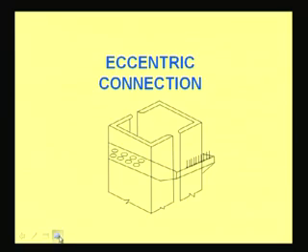Today onwards we will discuss the eccentric connection using those types of fasteners, that means the riveted connections, the bolt connections and the welded connections. The only difference here is that, due to eccentricity of the load, the fasteners have to be made in such a way that they can carry not only the axial load, but also the load due to eccentricity, the load due to the coming moment. Moment is developing due to the eccentricity, and that moment will develop some forces and some stresses in the rivet or in the weld or in the bolt. So, accordingly we have to design those with those constraints.